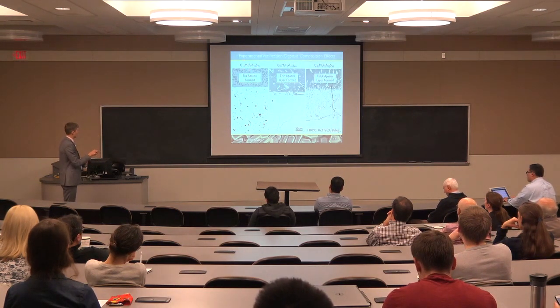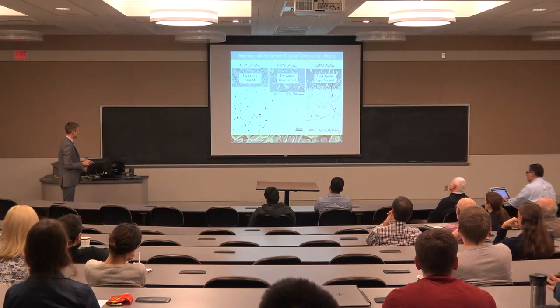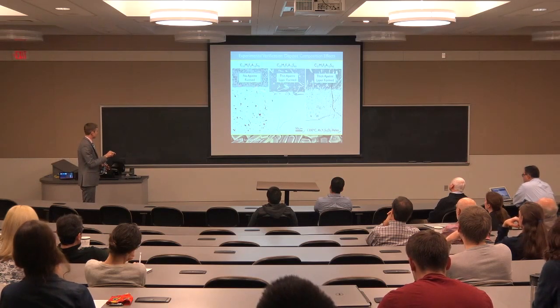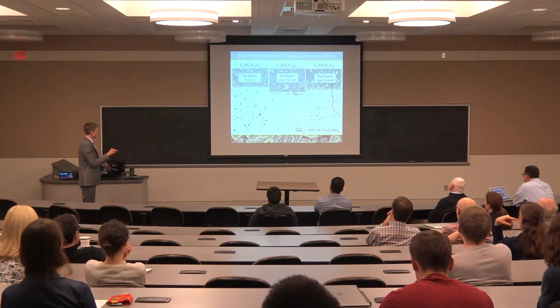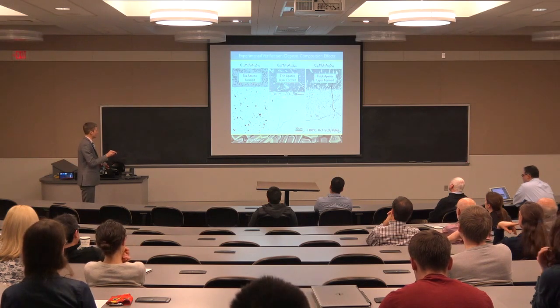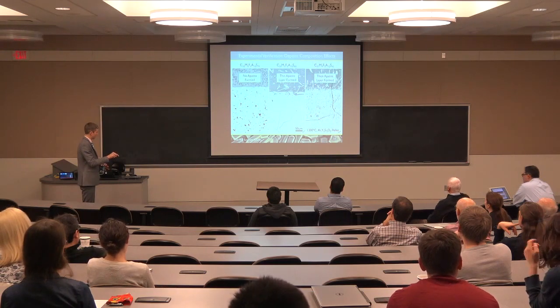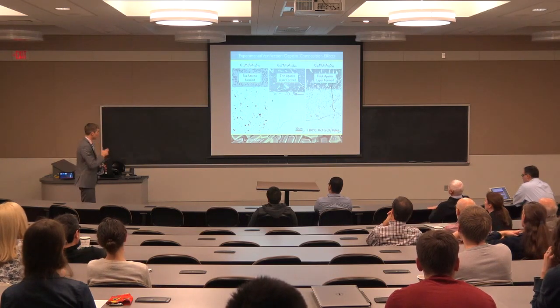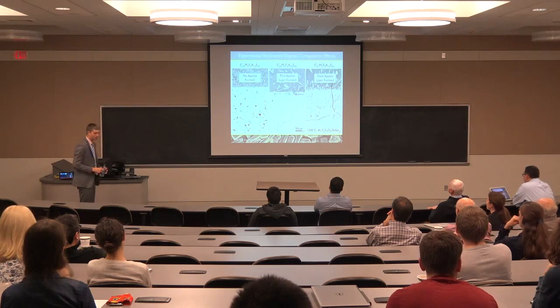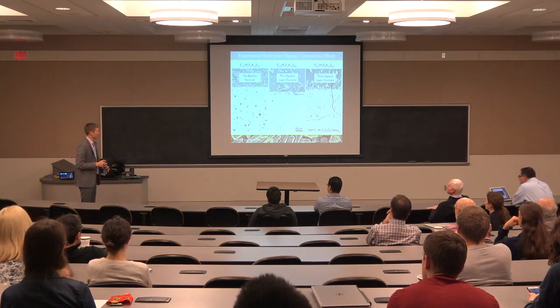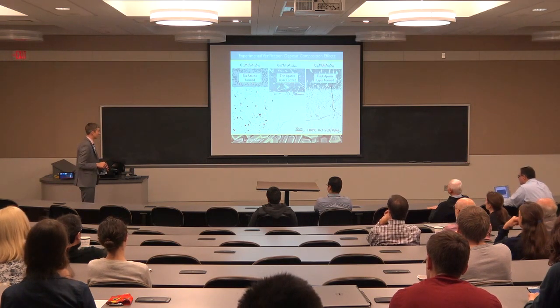So we pick these three different representative deposit compositions and in fact find that in the scenario where we expected no apatite to form, we get almost no recession, and that as we increase the amount of calcium in the deposit, the amount of recession increases. So here we get a little bit more, and here this line roughly shows how much of the coating has been consumed by this process. If we keep in mind that these coatings are usually only a few hundred microns thick, this is most of a coating in 4 hours. So obviously this is a particularly aggressive case.